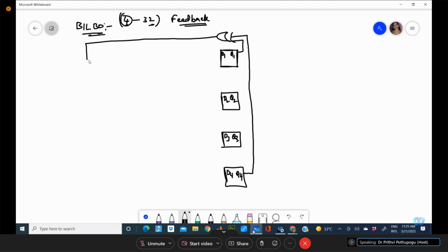Now I'm taking that as a feedback path. I use a multiplexer to choose whether it is the feedback path or an external input, because we said the modes are linear feedback shift register, multiple input signature register, normal shift register, or normal operation. A shift register means moving data between these elements. A normal operation is external input getting dumped onto your registers, something like a serial input.